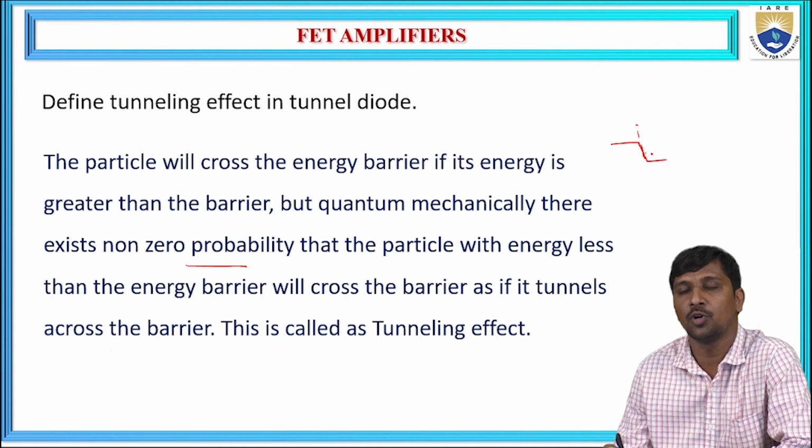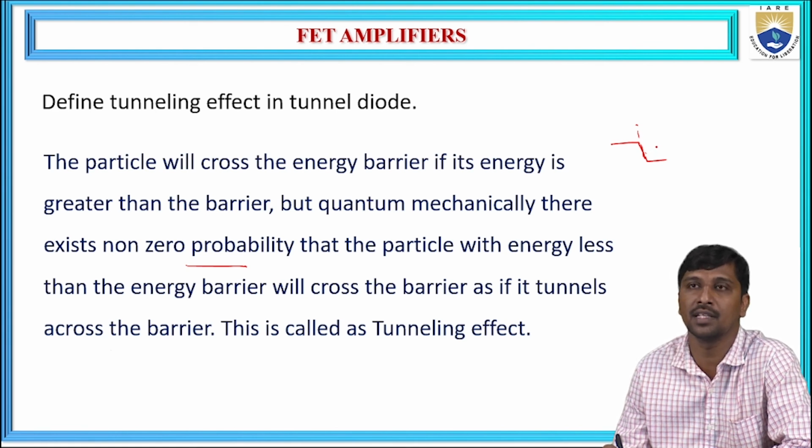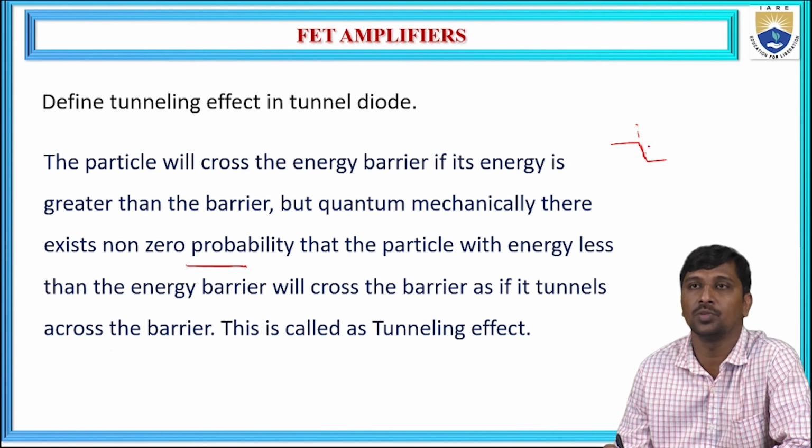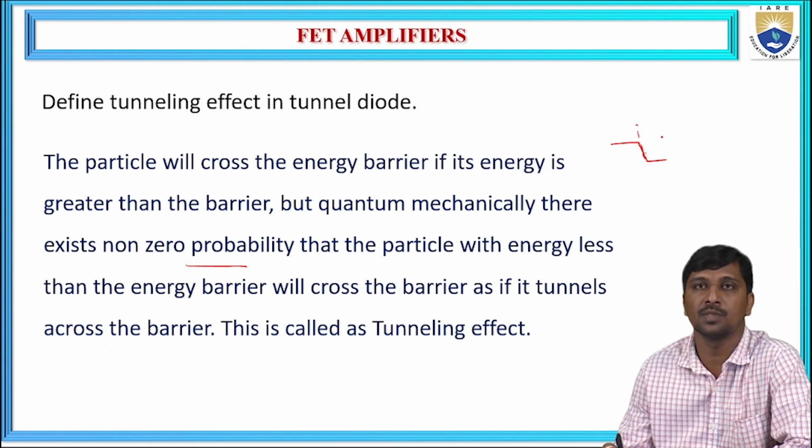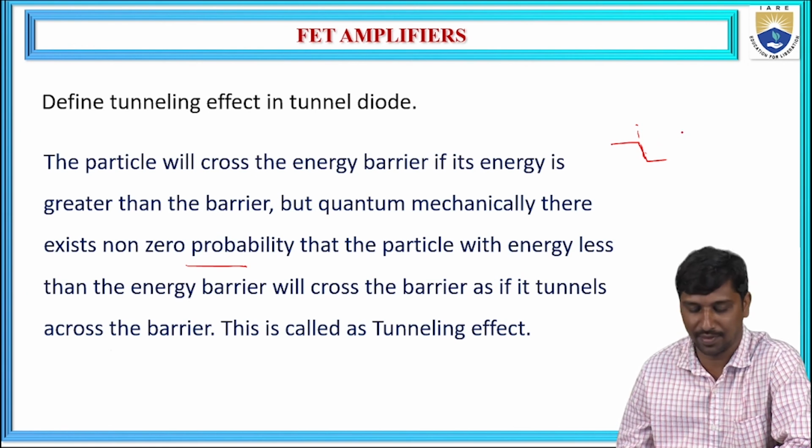If the doping increases, the Fermi level shifts. At that point, the energy band becomes like a tunnel, so a larger number of charge carriers move from the cathode to the anode side to allow maximum conduction. That principle is called the tunneling effect.